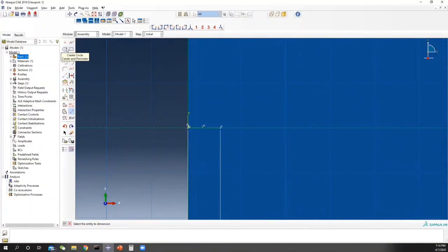And then we need to draw the contour circle. To draw the contour circle, we select this end and select another end on the horizontal construction line. Please make sure that the second point of your circle is on the construction line, so that later it's easier to make the partition. So now use the dimension tool. Let's make a 0.02 inch radius. So this will be our contour line.